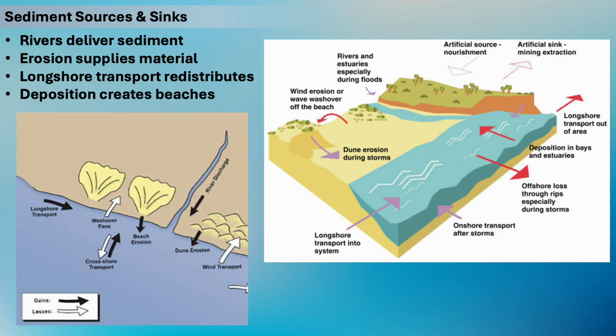For example, if a river supplies large amounts of sediment, beaches downdrift of the river may widen. But if sediment supply is cut off by, say, damming the river, beaches may narrow and begin to erode. So activities that are done on the river, even far from the shore, may have significant impact to the beaches.